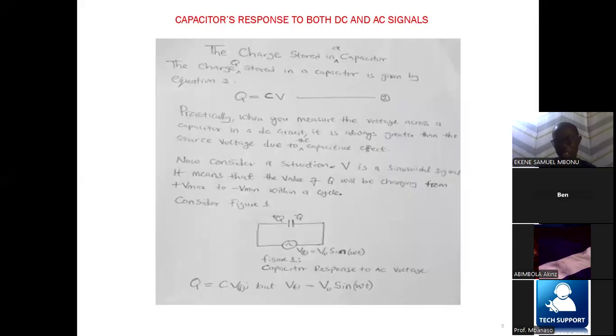And then if your capacitor is rated 16 volts by 1000 microfarad or 100 microfarad, you notice that you are subjecting that capacitor to stress because the voltage at that point is already above the rated voltage.